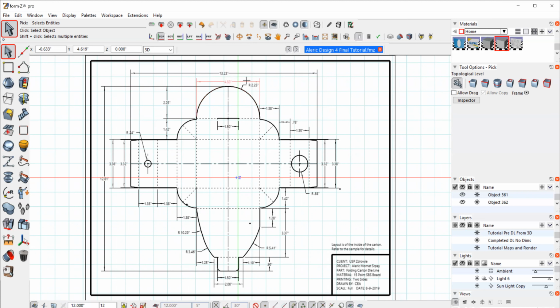So you see how this radius dimension fits inside of that one. Here I put it down on the bottom and did other dimensions up here. So it's a matter of getting all the, here, this is not correct. This one's over this line right here. I should actually move that over or bring it down into another location, because we do not want that witness line over the number like that. So that should be corrected. Okay, so this is how this all works. I think here I did this a little differently down here.